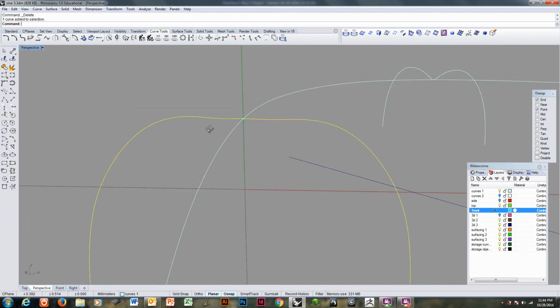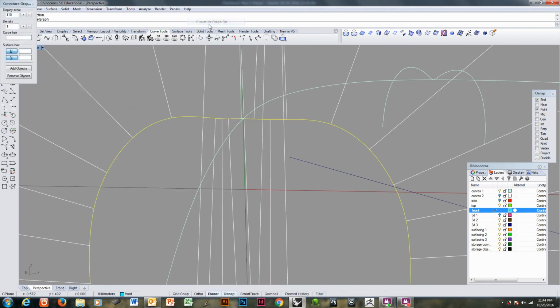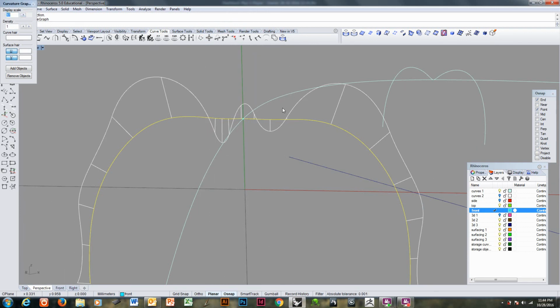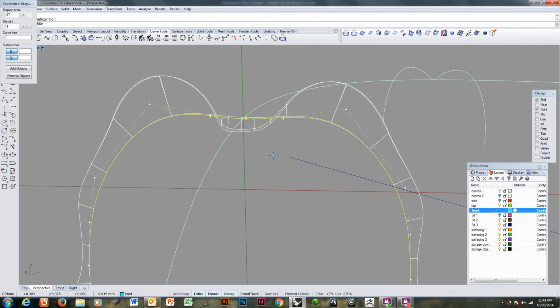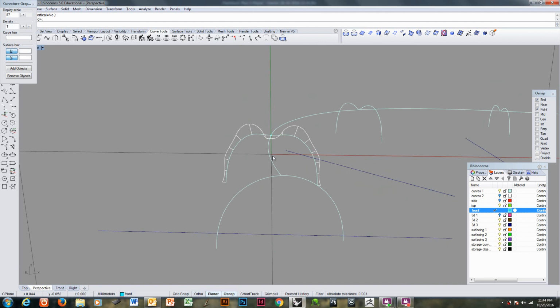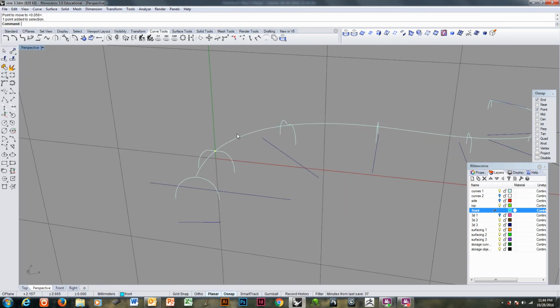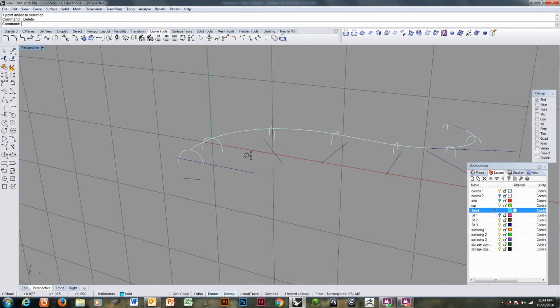I have a ripple in here I don't like. Analyze edge tool, analyze curve, graph on. See that? I don't want it, so bring my points back. And then grab the whole segment. Good enough. So I'm ready to now surface this.